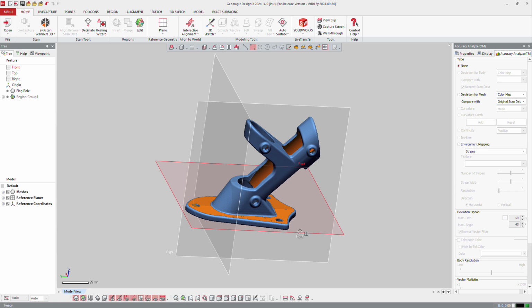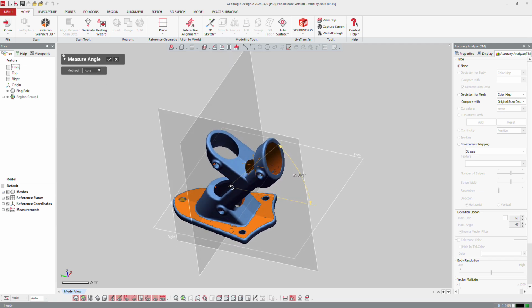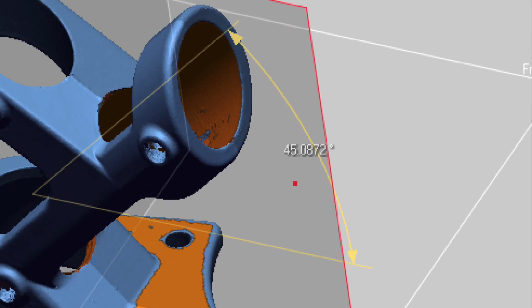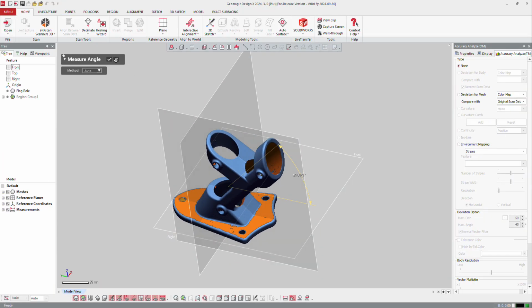As I'm going to make a parametric creation, I would prefer to have nice values. I don't want to have 2.35 as an angle. So I can check quickly the angle between that plane and the axis of the cylinder, and I got 45 point something. I don't like that. I want to have 45 degrees. It's a parameter you could get. So now I got that.